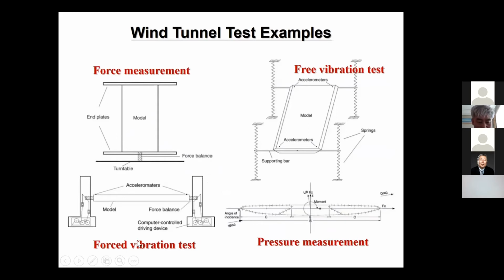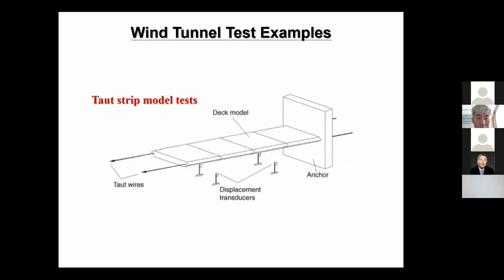Here we can also do forced vibration tests, and also some measurement on the bridge deck. For a bridge deck, the pressure measurement is not so common as on the building side, but still, in some cases, we have to do some pressure measurement for the bridge deck.